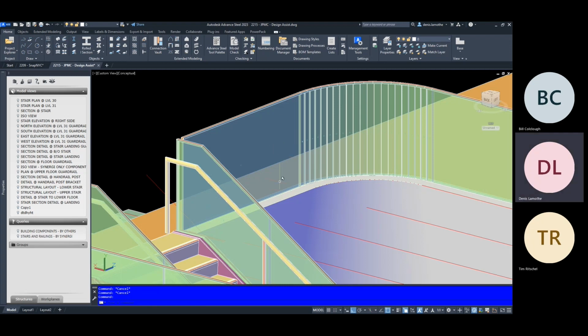Right, it buys us that little extra wiggle room where we can stay within code compliance and not have to worry about, oh crap, now we have to raise all our railings up a quarter of an inch because a guy put a quarter inch more terrazzo than we expected. So that applies to all our drawings.